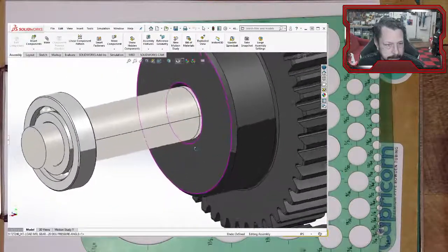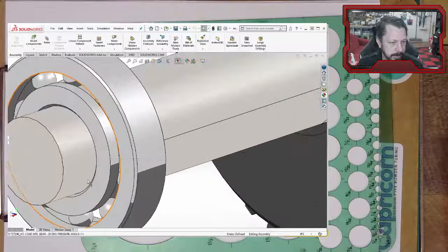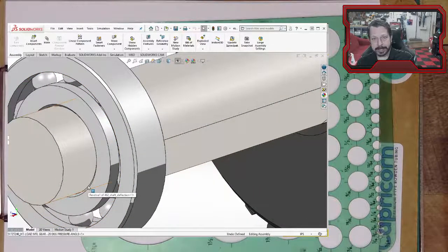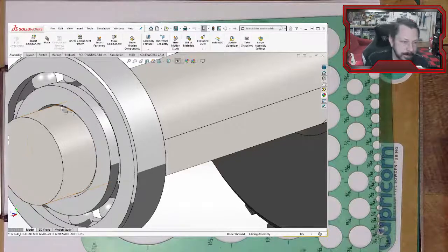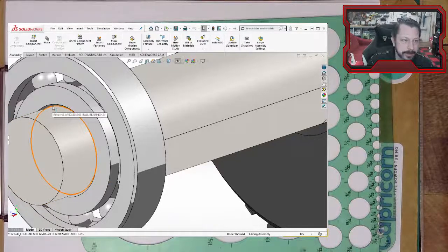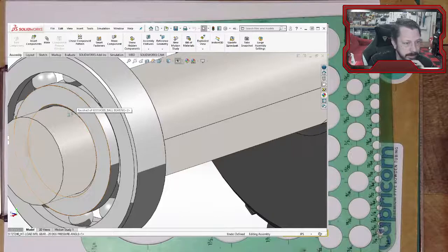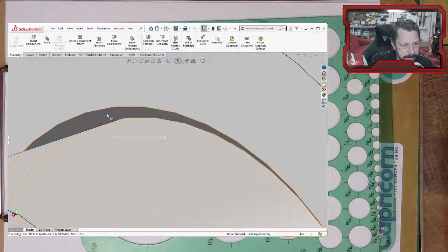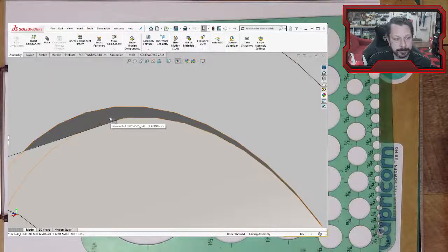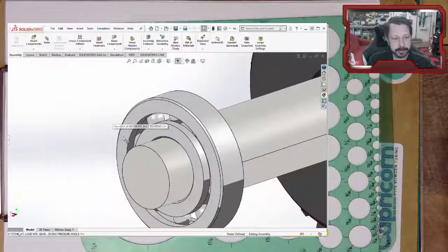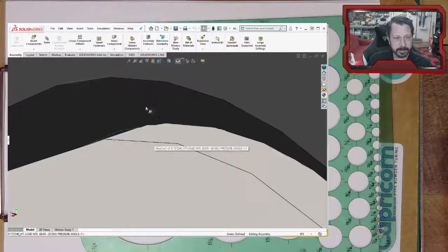One thing that these do show, let's see, I think the roller bearings probably show it easier. Last time we were talking about the fillet radius and how it couldn't be just this huge radius, even though that does reduce the stress concentrations. You can't have that huge radius because the element, in this case the bearing, has to sit up against the shoulder. And so how they do that is, if we zoom really in, you can kind of see this little chamfer right here. That chamfer is giving clearance for the radius. So assuming you know this chamfer, then you know the amount of radius that you can have on those steps. And these gears have that same thing in their hub also. There's a little chamfer.